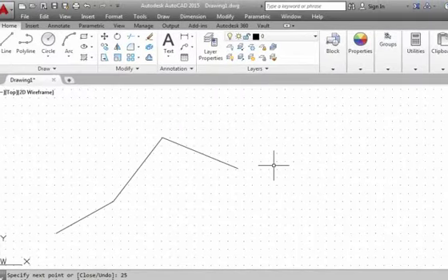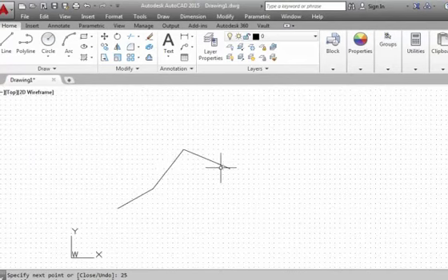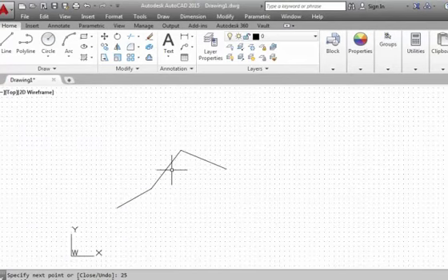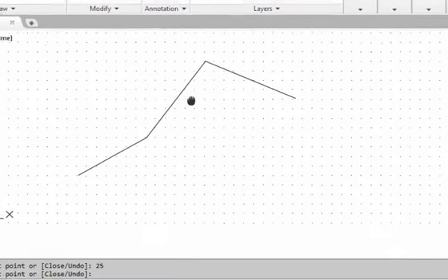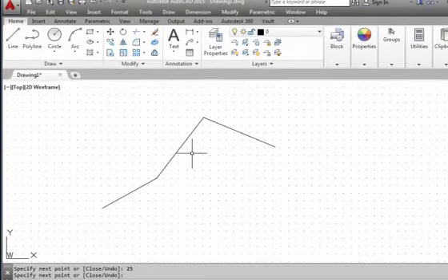In AutoCAD, the mouse wheel is also used to control the display in the graphics area. Turn the mouse wheel and we can zoom in or zoom out. And we can pan by pressing down the wheel and dragging the mouse. These are what is known as the dynamic view function that can be used to adjust the display of the constructed entities.